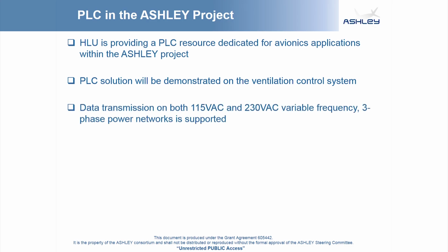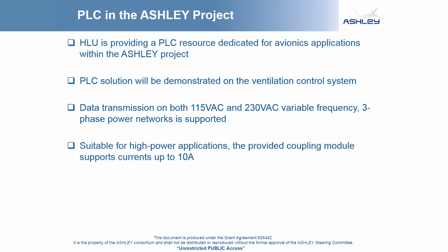A single solution supports data transmission over both 115-volt AC and 230-volt AC variable frequency, 3-phase power networks. The provided PLC coupling module, which is suitable for high power applications, supports currents of up to 10 ampere on those networks.